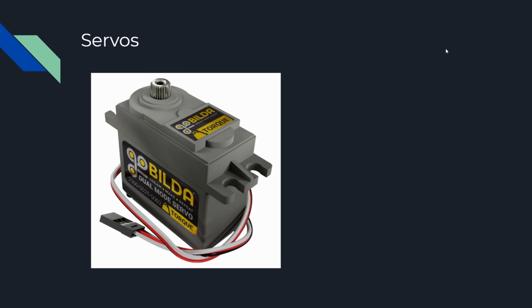In this section we're going to be talking about running servos. Servos are usually broken down into two types: continuous rotation servos and regular servos. In the picture you can see here, this is a dual mode servo, which means it can act as either a continuous rotation or a regular servo. And really the difference here is that a continuous rotation servo will spin freely, you'll set the power and it'll just spin freely, whereas a regular servo will spin to positions within a certain range.